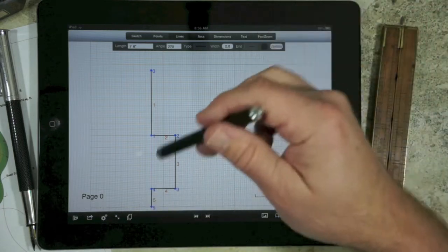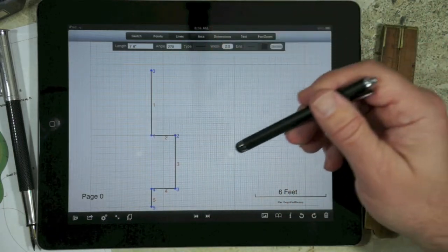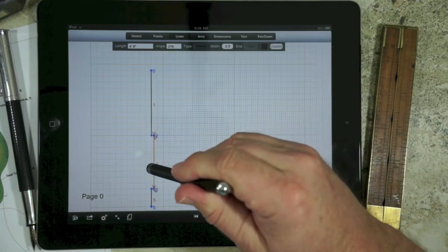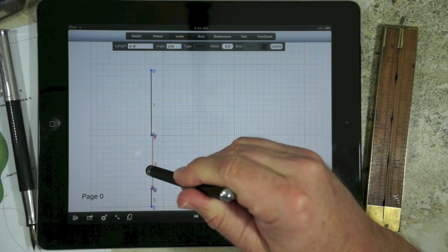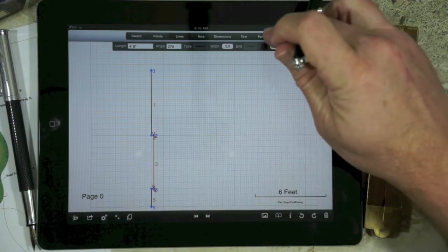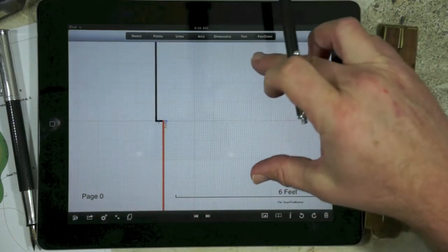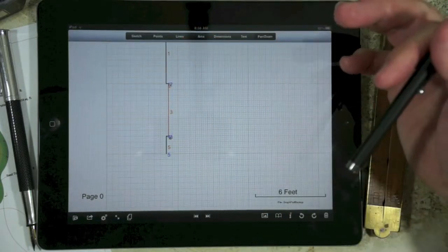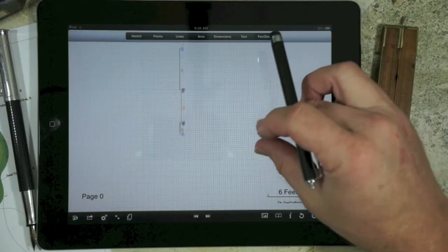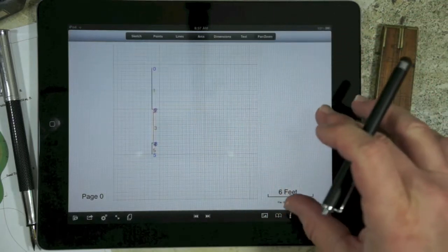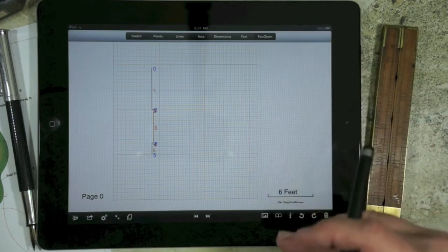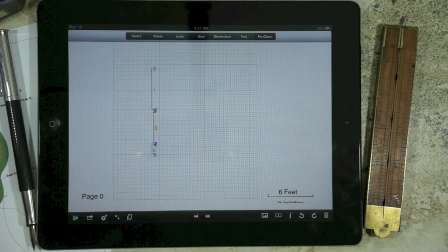And now in order to get, say for example, this was only a 1-inch gap or a 1-inch extension, if we grab that line, we can now move it in to where it's a very small distance and still retain our accuracy. And we can zoom in, we can actually see that. But if we tried to actually create those real small lines, that's going to be very difficult. So that's how you create really precise drawings using this tool, is to make it kind of big and then shrink it to where it's precisely where you need it to be.